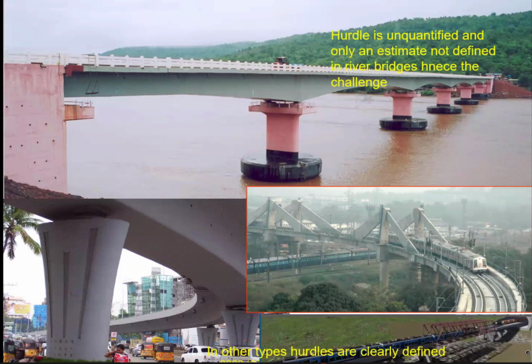But in case of river bridges, we are dealing with planning of a bridge over a hurdle which itself is sort of an unknown, because this discharge, which we call design discharge, is basically only an estimate. If there is an underestimate, then the project is likely to be irrelevant in future. If there is an overestimate, then we are going to land up with huge cost. So an optimal hydraulic design will lead to also an optimal structural design.